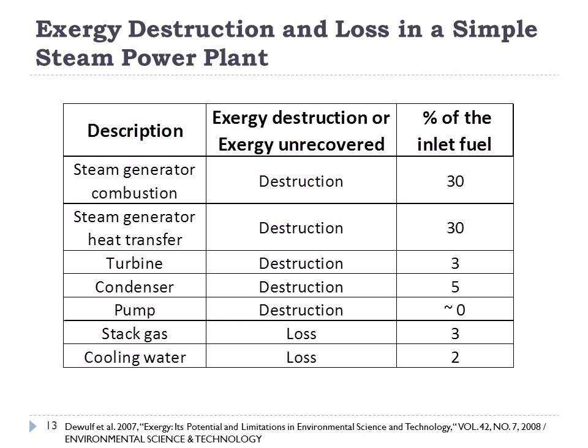I want to point out the other sources. To get this to sum up to 100, you have to look at the fact that there's still some exergy in the flue gas as it leaves the stack, meaning as it's put out into the environment. There's still typically about 3% of the exergy. You could try to get some more energy out of that, so you could try to go after that exergy.